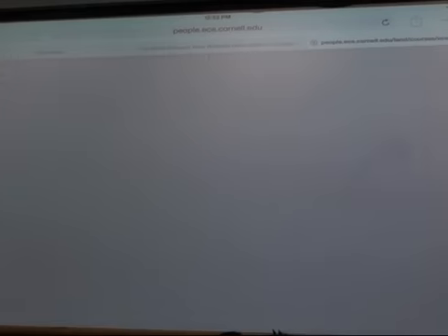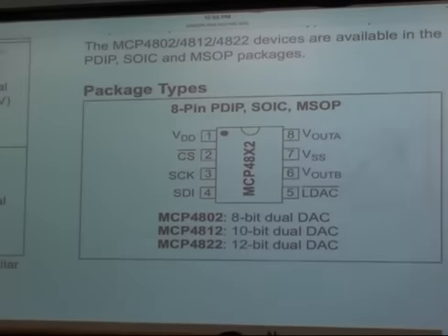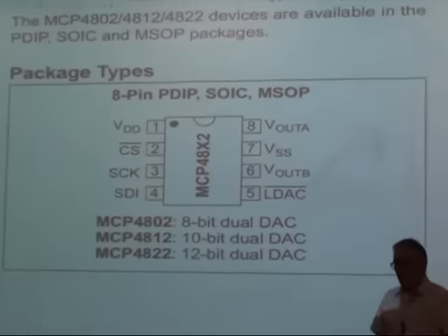Typical applications, power supply considerations, single supply operation. Make sure that you read this. Should you put a capacitor across the power supply leads? Should you? All right, I like both answers. If it says to, and why not? And the answer is yes.